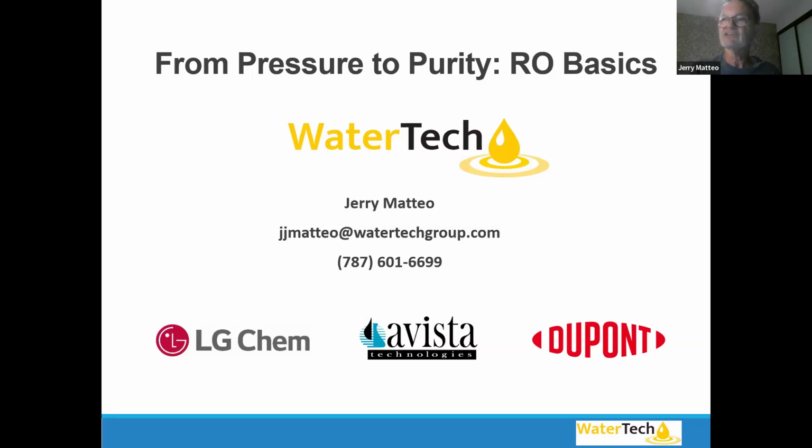Ocean intake is very expensive. You've got to run lines way out there to get clean water. So oftentimes you don't run it way out there. You have the intake closer to the land, and you might have passing ships or currents or things you didn't account for that can bring in sand. And sand is a killer. The two killers on seawater are particles from sand and also biofouling, because of all the living organisms in ocean water. So beach wells typically are much lower in turbidity.